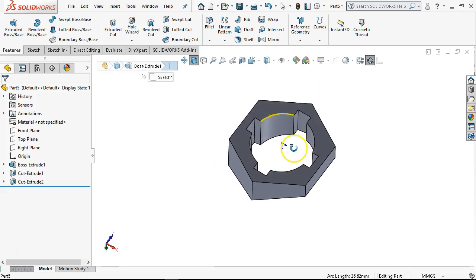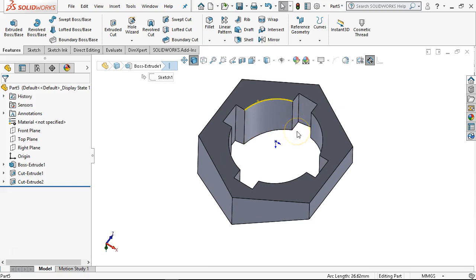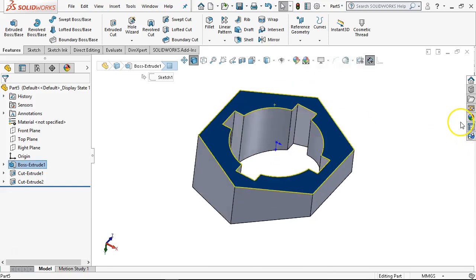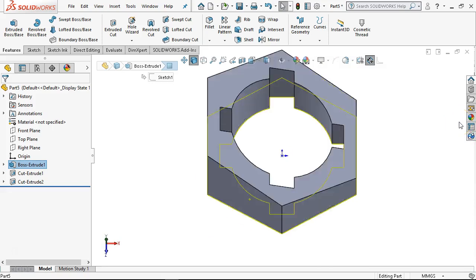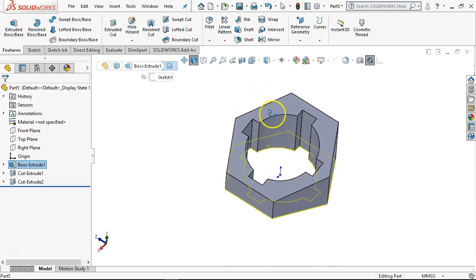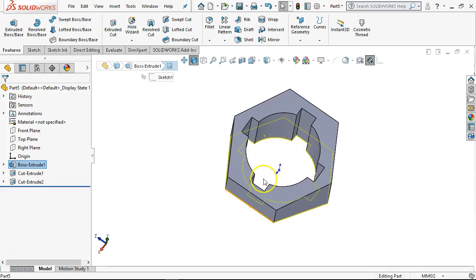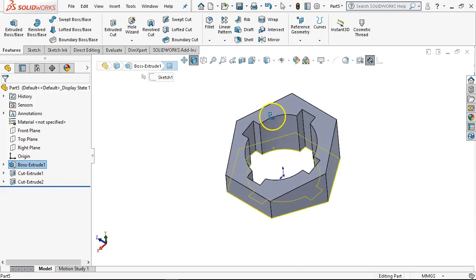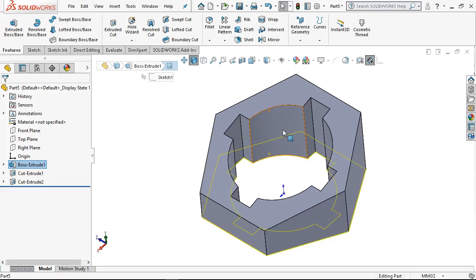All right, so arc length. When you see arc lengths as opposed to radiuses, that's telling me that that is elliptical in shape. All right, so just a little bit foreshortened. And the issue here is that I can't just put a drill bit, and, well, let's see, at 50 millimeters, we probably have the fitting to broach those. You know, run them through the arbor press and just knock those out. Since we're dealing with the notches, we're probably going to have to wire EDM it anyway.